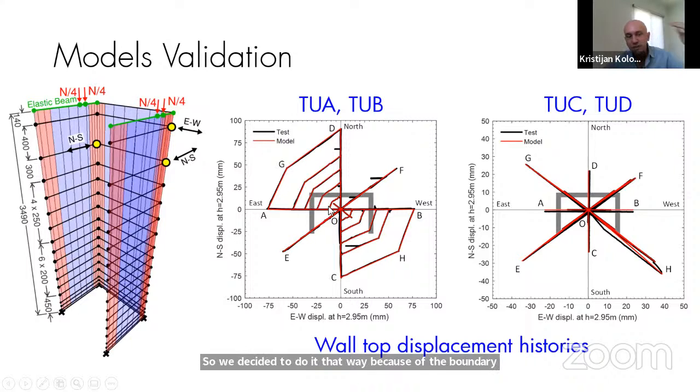The reason you're seeing a list of different force control analyses is because the loading is changing direction, right? You see first I'm pushing up and down, then I'm pushing left and right, then in fact I'm pushing this sweep like this. So each of the segments is a separate load of force control analysis. That's the reason we have so many different ones.